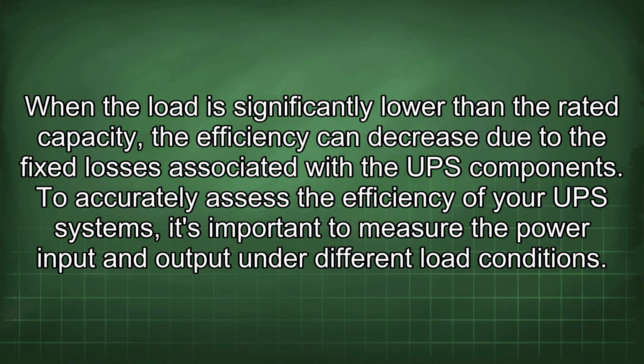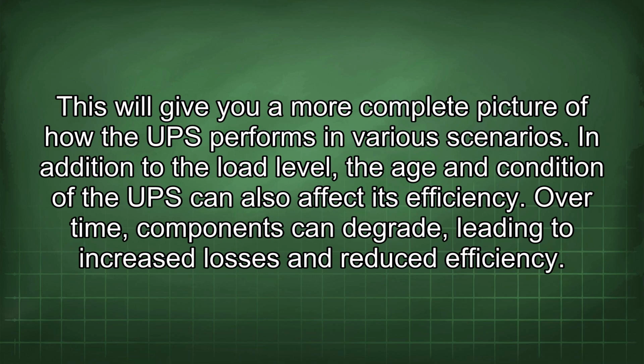When the load is significantly lower than the rated capacity, the efficiency can decrease due to the fixed losses associated with the UPS components. To accurately assess the efficiency of your UPS systems, it's important to measure the power input and output under different load conditions. This will give you a more complete picture of how the UPS performs in various scenarios.